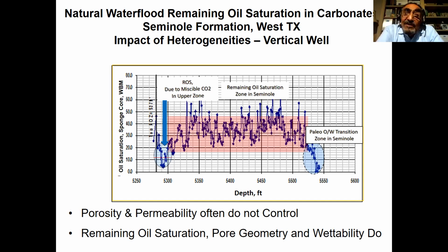Also gas injection, generally, if it is different from being very close to the reservoir fluid, causes asphaltene dropout. If you do asphaltene dropout in a shale formation, basically you're plugging the formation. So you have to be very careful what type of gas is being injected. You can inject nitrogen or inert gases, but then that is exactly what is causing the asphaltene dropout. So it requires close rock-fluid collaboration in order to do this design, such as a laboratory design.